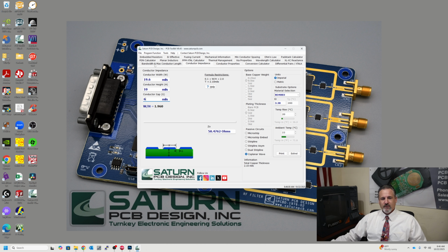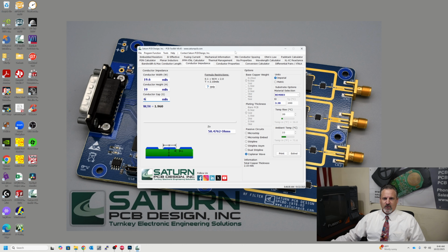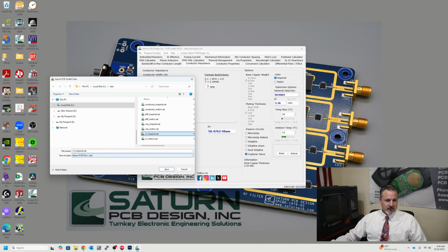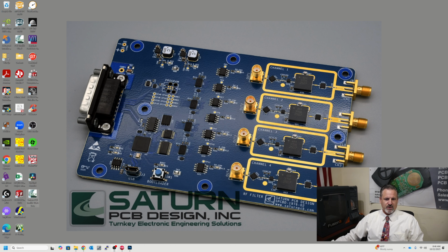We want to save this configuration. We use the Rogers material all the time, and this is going to be what I want to use going forward for other projects, or I want to send it to someone else who has a PCB Toolkit, one of my coworkers or whatnot, so I can export. And we're in Imperial right now. We'll call this Z Imperial RO 4003. Okay.